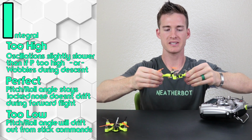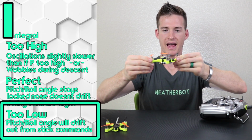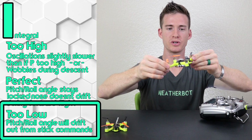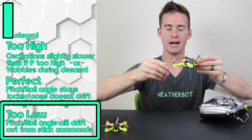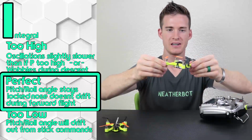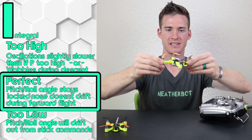And what you're going to notice as you're hovering and giving some small inputs forward and backward is that it's going to try to drift on its own, without you giving any inputs. The angle will drift, and the more I you give, the more it's going to tighten that up, and it won't drift. Eventually it'll stop being really sloppy, the angle will stop drifting, and it'll be very crisp. You give it an input, and the angle will hold right where it is.